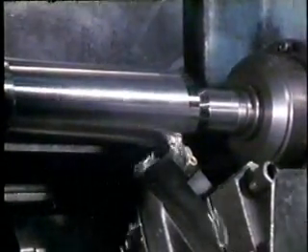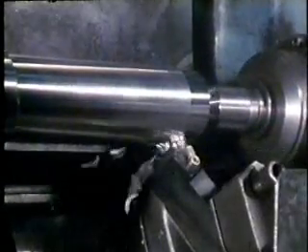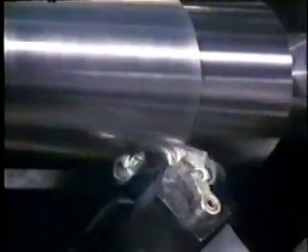Ceramic tools are used mainly for finishing cuts at high speeds and fine feed. Cutting speeds of up to 300 meters a minute are quite common. Under these conditions, ceramics can produce excellent results, but because of their brittleness, they are seldom used for intermittent cuts. This is due to the high forces involved, which can cause the tips to shatter.